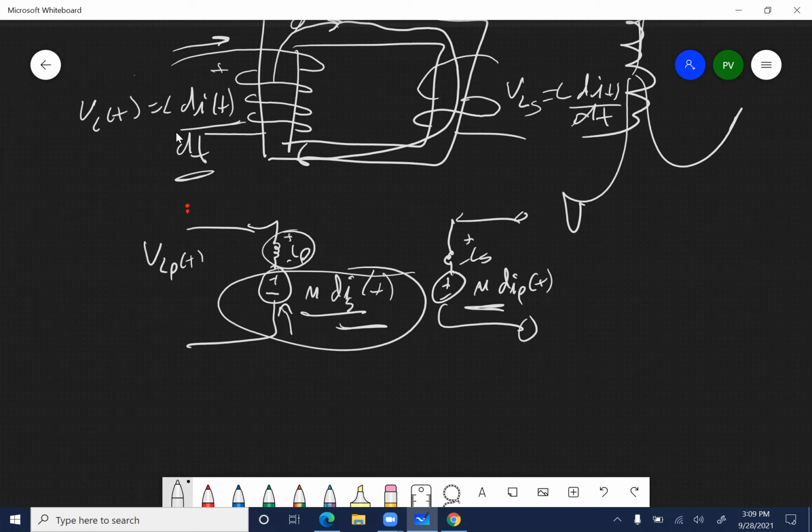And you can go up and down in almost unlimited ranges. The biggest one I've seen is 13.8 kV to 345,000 volts. That's the biggest step change that I've seen, but they might have bigger ones out west. The ones I'm talking about are generators. Some big generators and some medium-sized ones operate at around 13.8 kV, and oftentimes they'll step up. If it's a big enough generator, it'll step up to 345. So you're going up, what is that, 20, 30 times the increase in voltage. And at that point, it's just the number of turns.